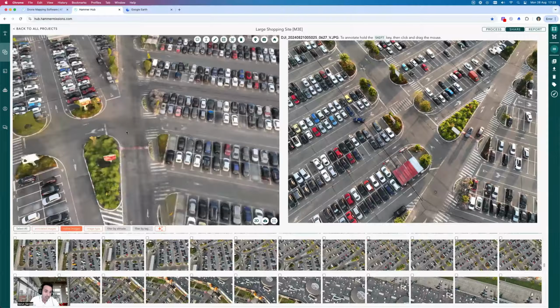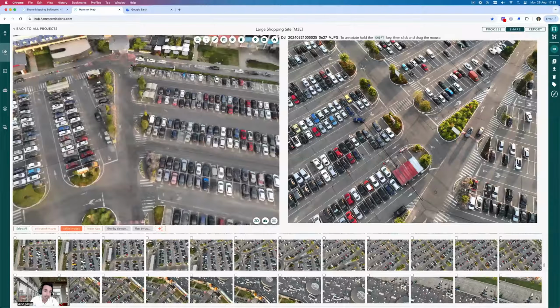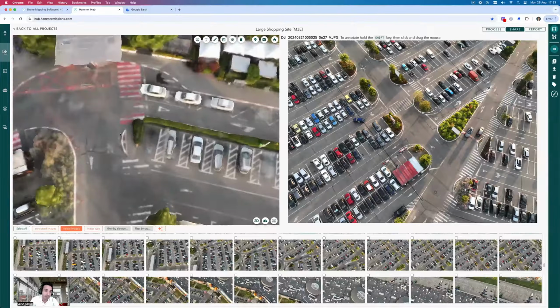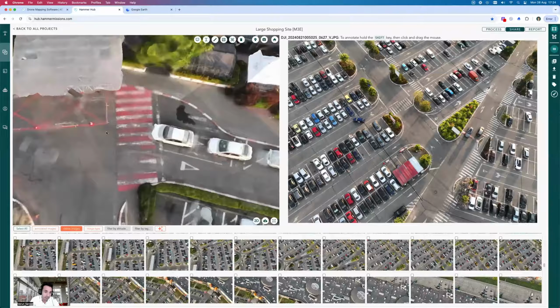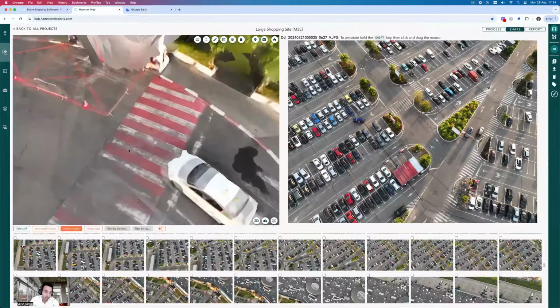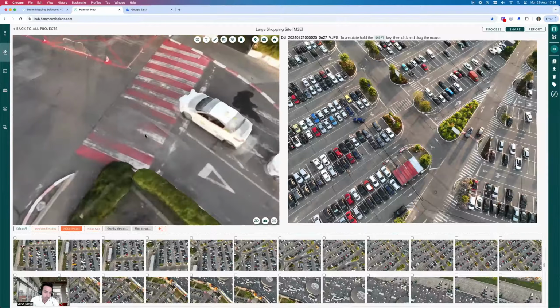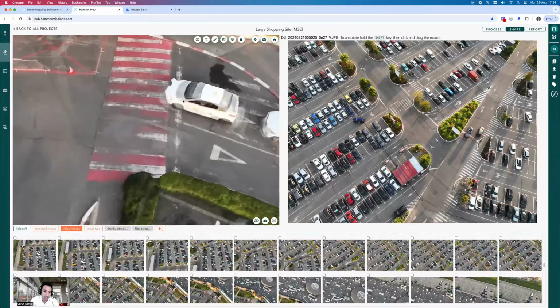And to understand the slope, you can go in and measure the slope of any of the existing structures. So for example, over here, if you've got any of the slopes, you can go in and drop 2 points on the 3D model, and then you can get the slope between those 2 points and see whether that slope matches your requirements.